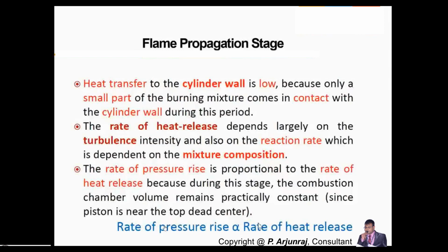Before 20 degrees TDC, the fuel gets ignited, the spark gets ignited, and once it gets ignited, you have a delay period or ignition lag period. After the ignition lag, the flame gets propagated. During flame propagation, the piston moves from TDC to BDC, for example, and that is where the real combustion happens, the power stroke. It is nothing but the power stroke.